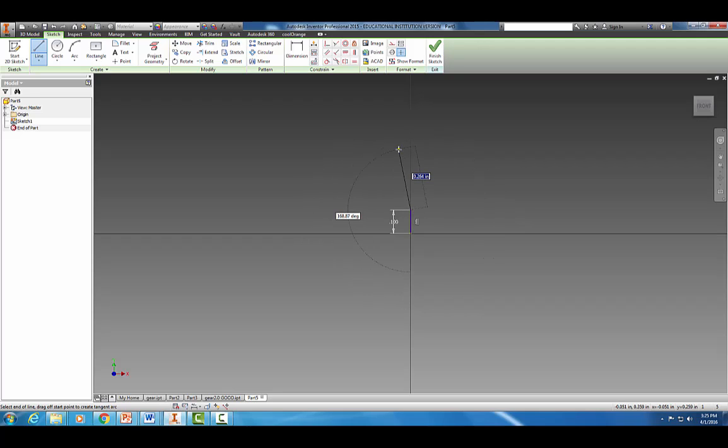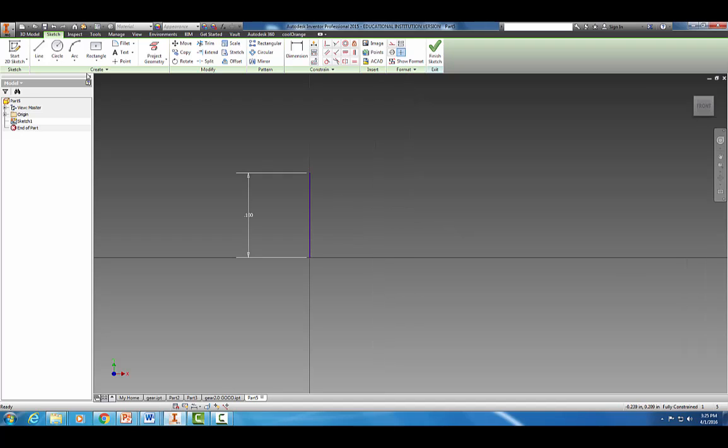All right, and now we need to make the radius. Not the diameter but the radius, which was 0.108. Enter. Okay, hit escape. Now come up to our circle. This is the thickness of your spring metal, the thickness of your coil metal here. I got a length of 0.02 when I measured my spring. Go ahead and hit enter.